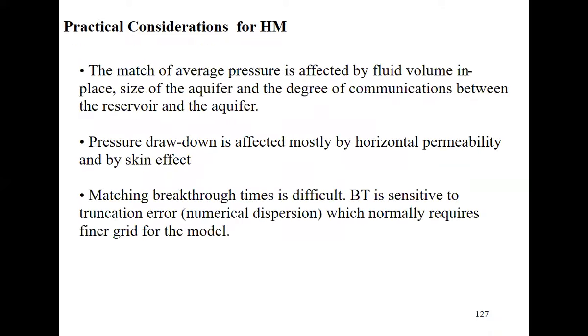The match of average pressure is affected by fluid volume in place, size of the aquifer, and degree of communication between reservoir and aquifer. So the pressure is supported by this pore volume, aquifer size, and communication between reservoir and aquifer. That's why I said before we may change pore volumes to match the pressure. We may change our aquifer size, aquifer volume, and also the transmissibility between the reservoir and the aquifer.